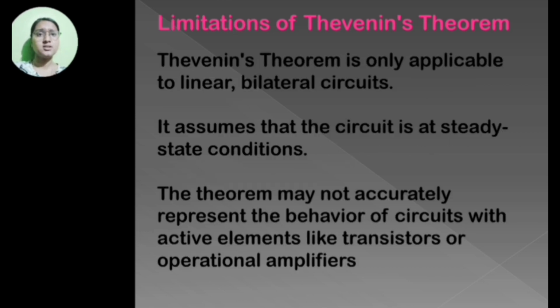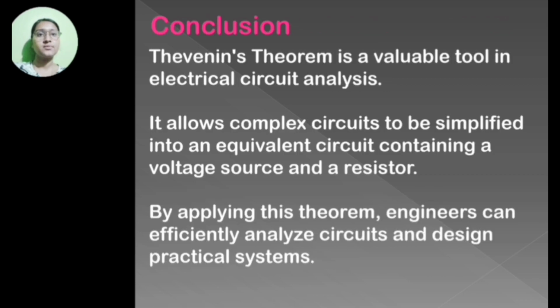The limitations of this theorem are: Thevenin's theorem is only applicable to linear bilateral circuits. It assumes that the circuit is in steady state conditions. The theorem may not accurately represent the behavior of circuits with active elements like transistors or operational amplifiers.